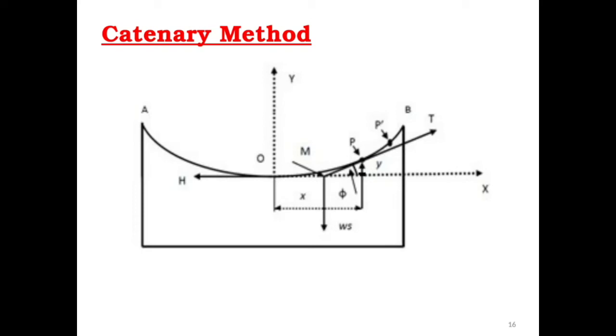In the notes that I put on the Moodle website, all the calculation is shown. It's a complicated series of steps, doing all these derivatives. We get the equation for that, and in this one we calculate the actual length of the conductor. We can calculate the tension at any point of the conductor as well.